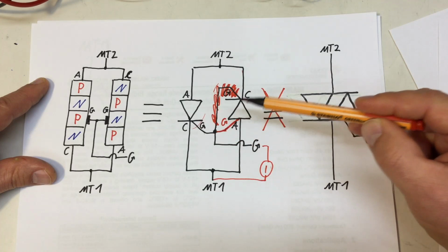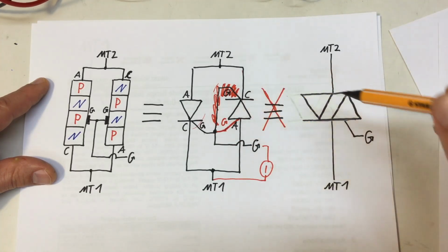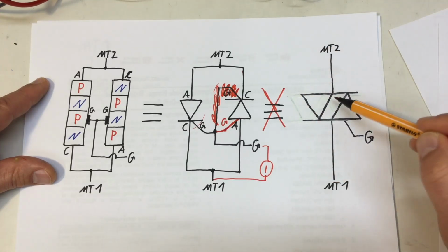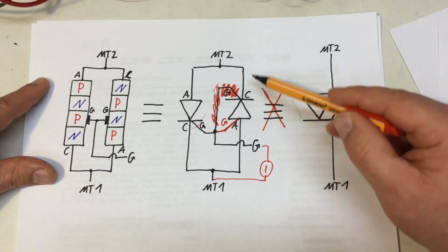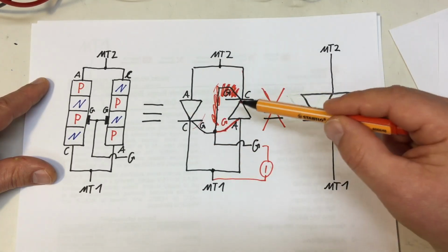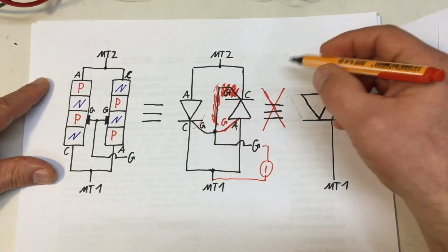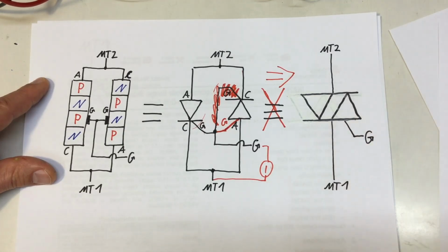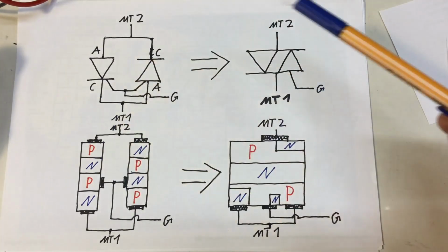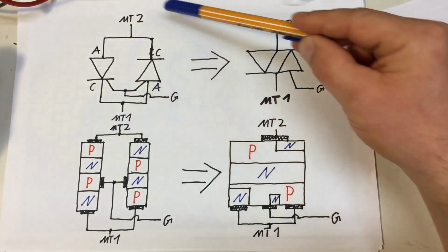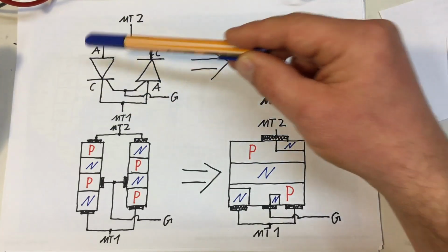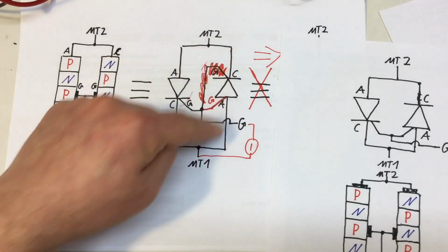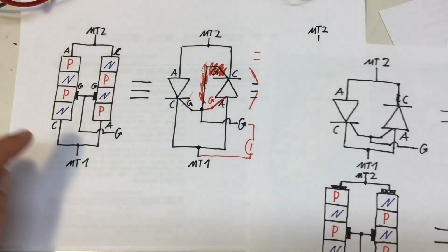I could run it. It's still not behaving exactly like a thyristor, because we've seen a thyristor works in 4 quadrants. That thing only works in 2 quadrants. But yeah, we can say it somehow leads to a thyristor. In a proper textbook you will find something like that. You already know that picture here, 2 reverse parallel SCRs, one P-gated, one N-gated. Yeah, that was our corrected version of that picture here.